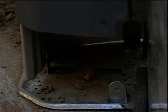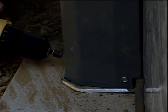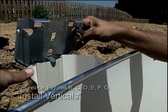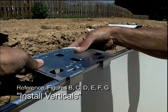Now attach the end vertical supports to the bottom end caps by using 10 by 3/8 inch long sheet metal screws. The pool you are assembling will determine the amount of screws you will use. Please refer to the assembly guide to locate this information about your pool. Assembly guide reference Install Verticals, figures B, C, D, E, F, G.